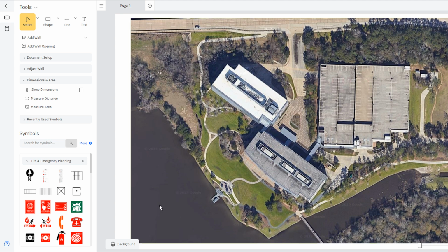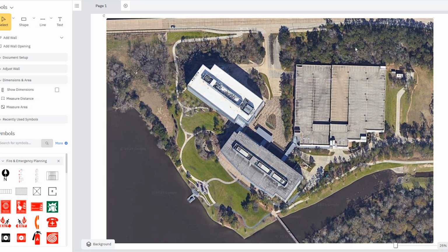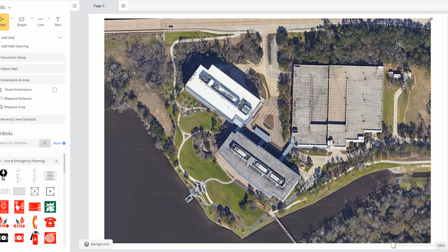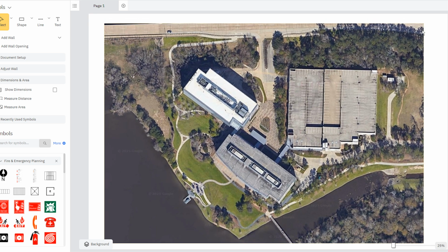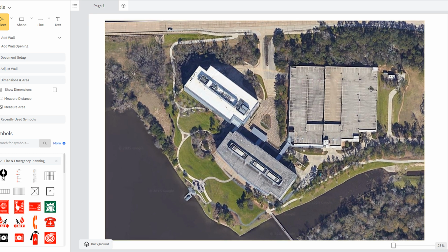You can switch layers and manage layers by clicking here beneath the work area. To help you scale the imported image, we'll want to match a guideline drawn in SmartDraw with an object of known dimensions from the imported file. So first pick an object that you know the dimensions of, like a map scale line, a corridor length, or a room size. Now draw a line that matches the length of that specific segment. Next, resize the imported image using its handles so that the feature in that image lines up exactly with your guideline. Once they align, the image is properly scaled to your drawing.